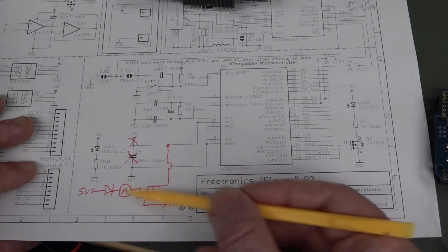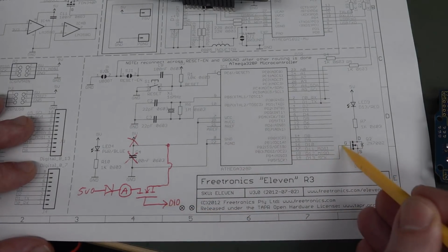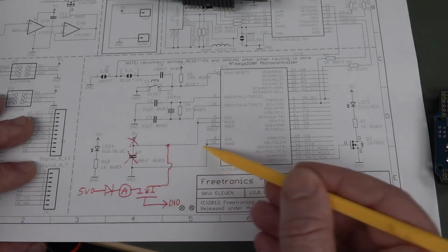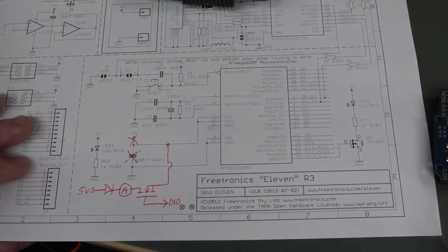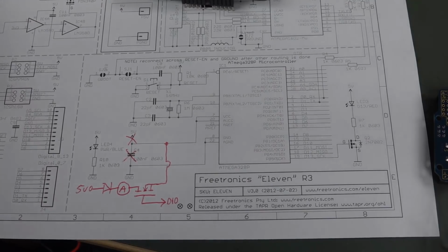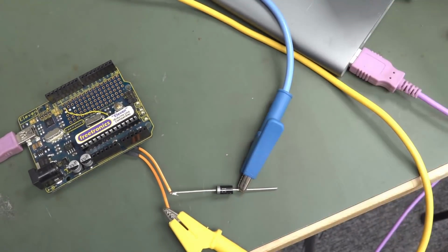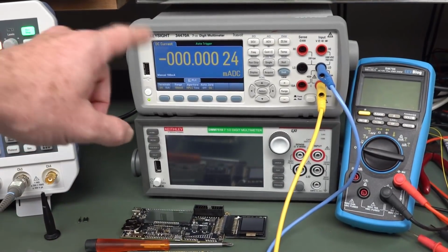We want to make sure we're measuring the current going into the processor, and then it just connects through to here. So the processor's actually going to switch its own power, which sounds insane, but diffusion capacitance allows us to actually do this, and we're going to get reduced power consumption. It's neat. So I'm powering this just from an external USB pack here. I'm breaking in here with our current meter, which is our Keysight up here.